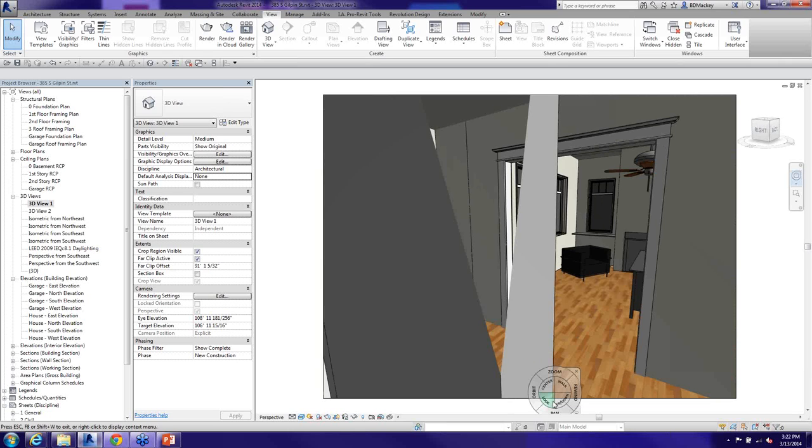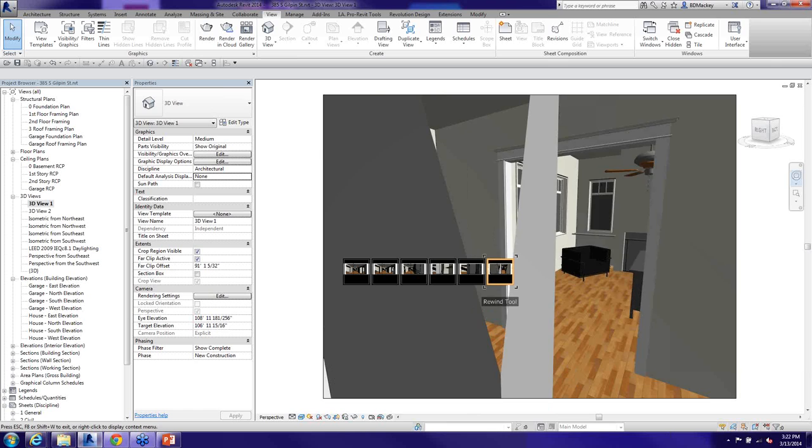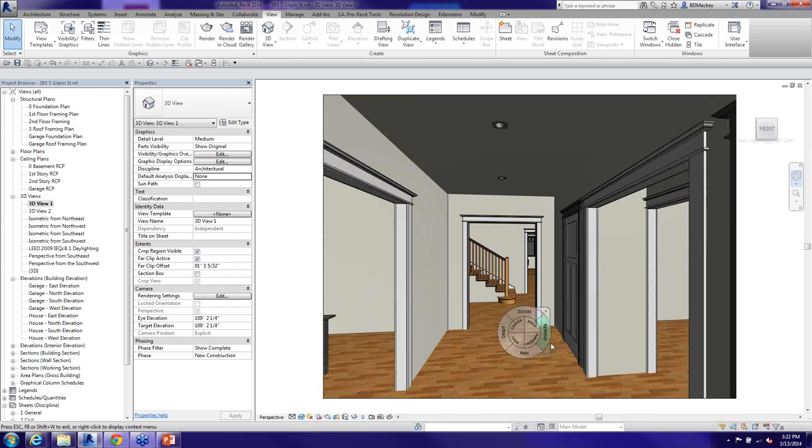I had one person struggling dramatically with renderings, and then we realized that furniture, our light fixtures, were turned off in plan, and they put the camera directly inside of the lamp. They spent hours trying to figure out where this really bright yellow haze in all of their renderings was coming from, no matter what they did, and we found out the camera was inside of the lamp, which had a yellow shade on it. It was kind of funny because we didn't see that in plan. It took me a while to figure it out too. So when you're going through and doing that, the steering wheel is really beneficial to see what's going on.